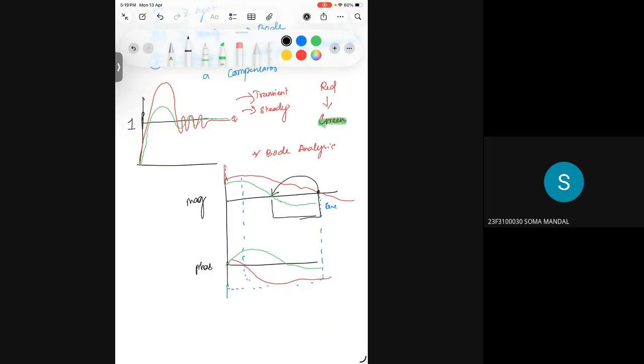I want to shrink it inside and I want to bring down my phase plot from here to here. That's what I understood from this. So for this difference between these categories, I am going to design a compensator. This compensator will act along with my plant to bring my Bode plot from an undesirable place to a desirable place, so that my time response or the output response will be good, the way I expected.